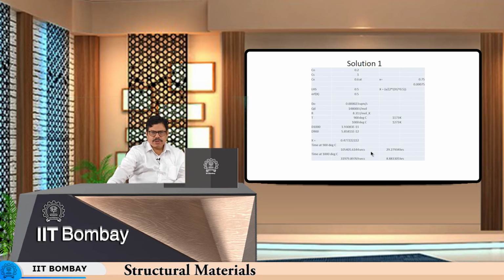material. So depending upon the composition of the material and the ductility of the material, one has to judiciously take a decision of whether quenching should be done or the heat treatment should be done at 900 degrees centigrade or at 1000 degrees centigrade. So it is not just purely these numbers and the quickness with which you can carburize the material that governs the choice, but it also has to do with the other considerations of the stresses getting induced in the material while doing the quenching operation or while cooling the material from that particular temperature. So even normalizing might be able to give you the kind of martensite, so it may not require any severe quenching, but still one has to be clear that the stresses induced during cooling are not going to be too high.